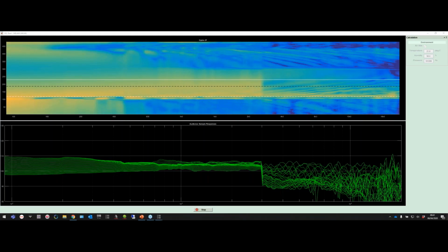So first of all, with these optimized systems, we are optimizing down to 160 Hertz, so there's group delay and latency involved there. All of these systems have a latency of 12 milliseconds. Therefore, using them as an on-stage side fill may not be the best solution. We have had customers and users in the past who have had no problem using it, especially for more dance-type events with DJs and things. As long as there's a delay offset on the headphone out of the DJ mixer, we don't have a problem. However, this could have an effect on stage with live musicians.